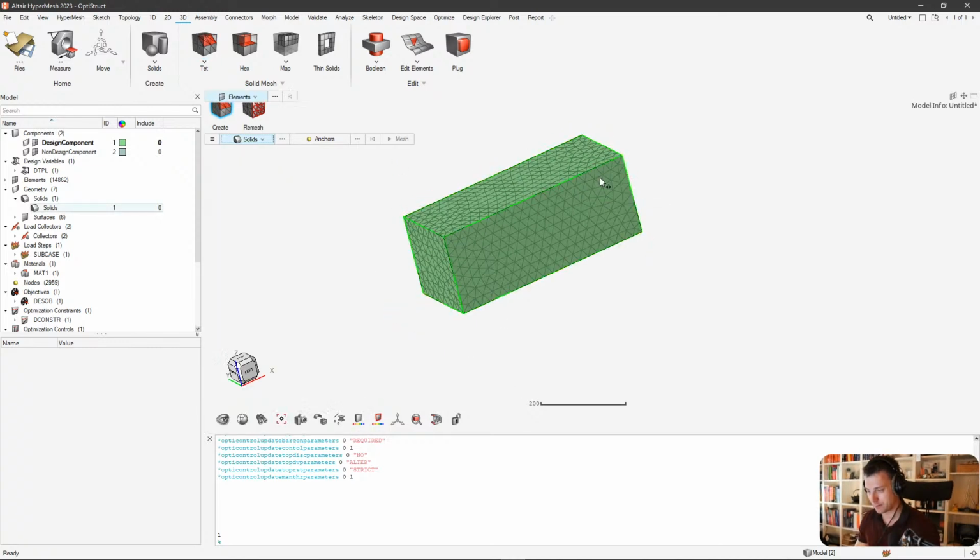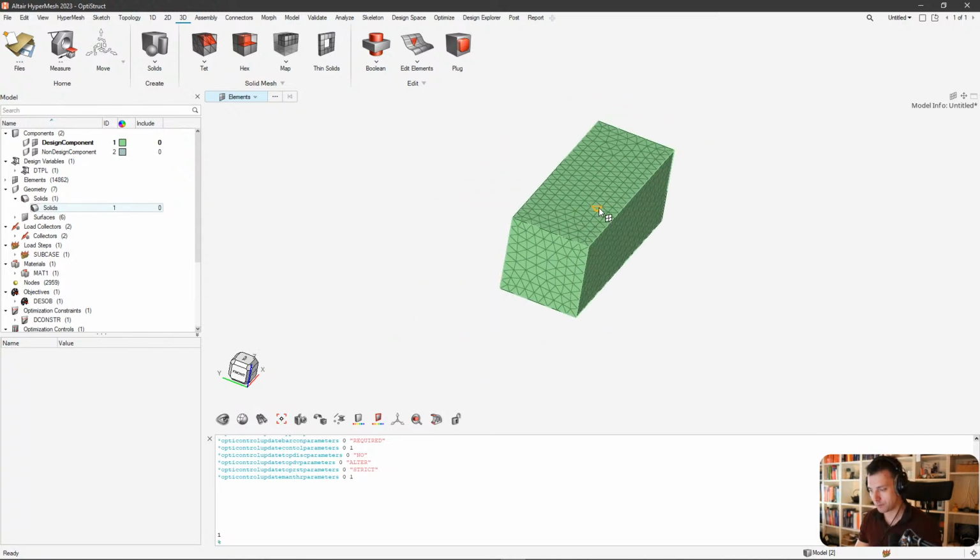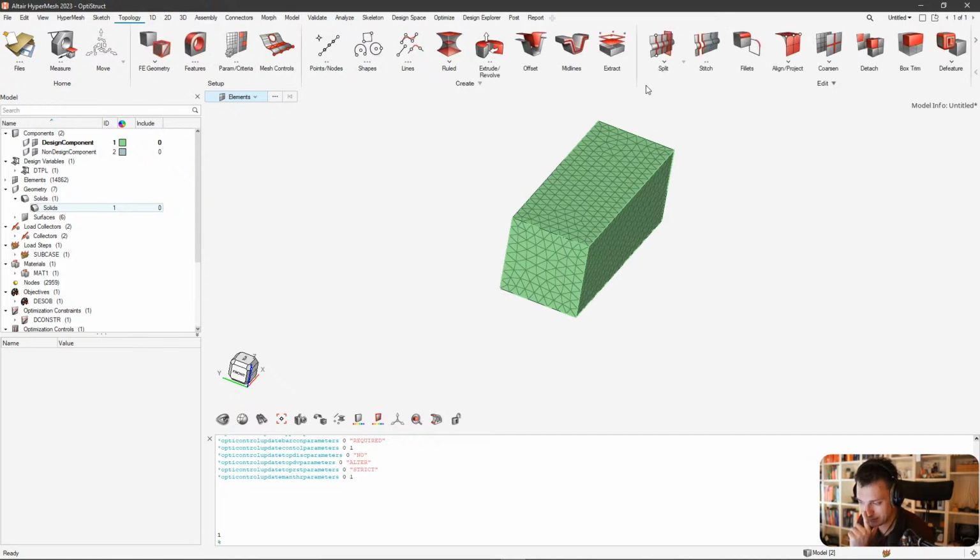All right, now that's about that. We have meshing here. Now, that would be a full model, but with shape controls, to be honest, we would have done the splitting first. So what I missed here is the splitting. I can do the splitting afterwards, but it may upset the mesh, because the mesh is already there. And if you now introduce a symmetry plane, you're splitting the solid into two, you force the mesher to put the nodes onto the surface.